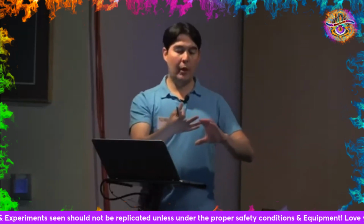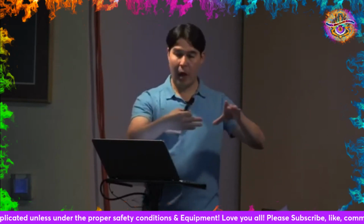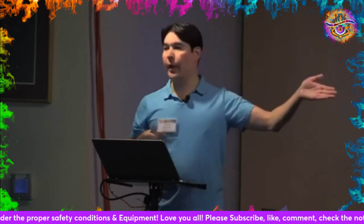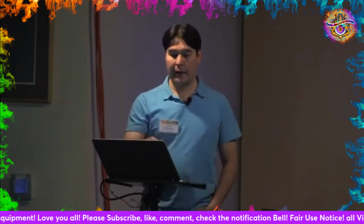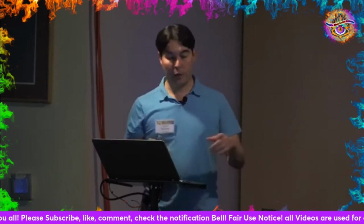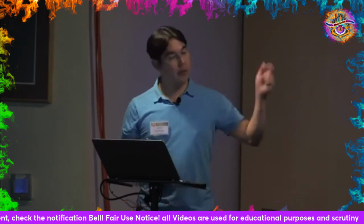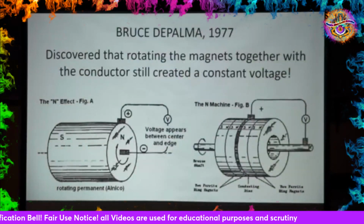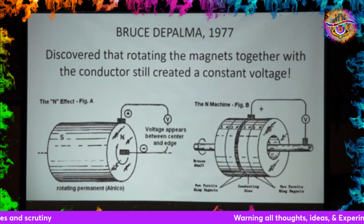So if you rotate the conductor and the magnet together at the same time, like on a common shaft, you're not supposed to be able to create any kind of electricity because they're not moving independently of each other. But the fact is that if you take a voltmeter and put the positive on the perimeter of a spinning magnet like this, and the negative on the shaft of the spinning magnet, you actually develop a voltage. It's not supposed to happen.